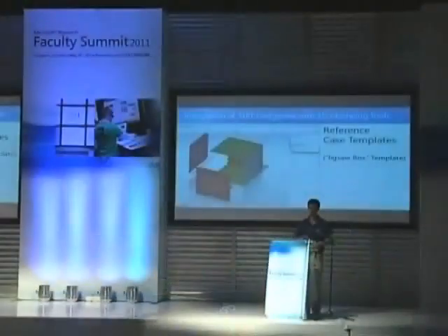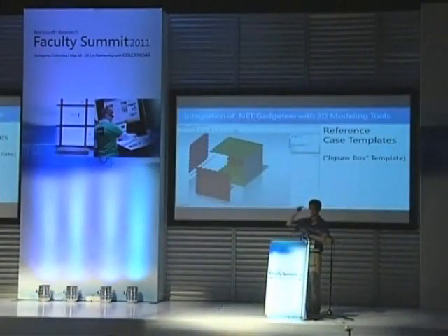because we think it's a key part of this process, this shaping, this constructing of the object. So what we have done is we're building some extensions to existing 3D design tools that let you very quickly construct a custom enclosure shape for your Gadgeteer electronics. This is a simple example where I'm starting from a template. You can create these things from scratch, but here I say I want a box, and I want the box in these dimensions.